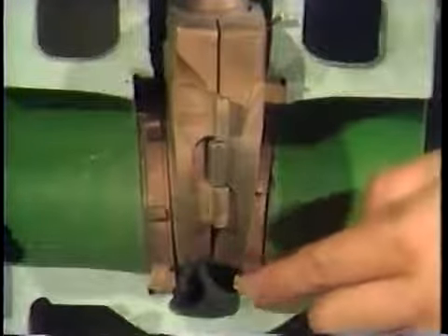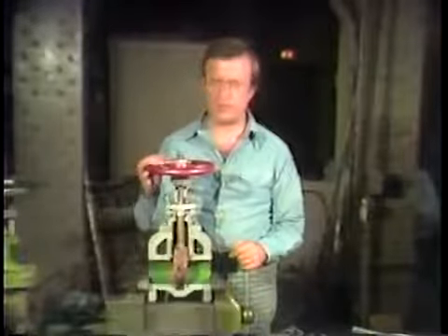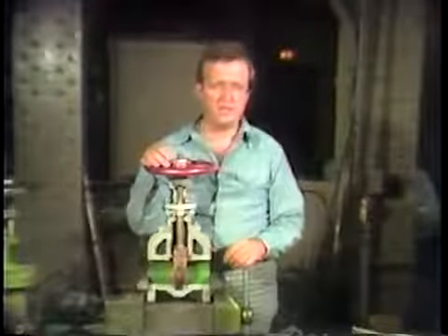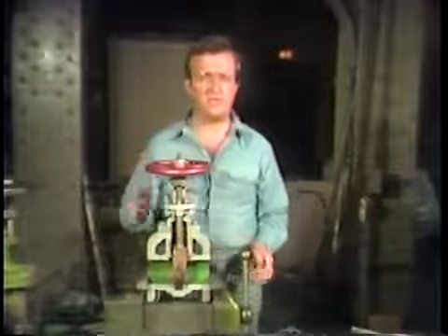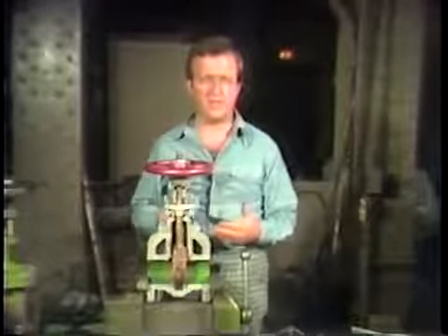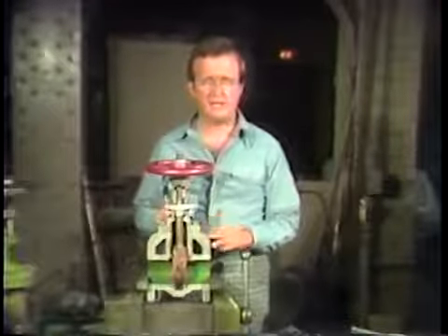The seats on a gate valve are either fixed, built into the body, or are replaceable like these. Small gate valves are usually made with fixed seats, while large ones most often are equipped with replaceable seats. This is a practical consideration. Small valves are not usually welded into a system, but large valves are. So if the seat on a large valve is replaceable, the valve itself can stay in place and the damaged seats are replaced.